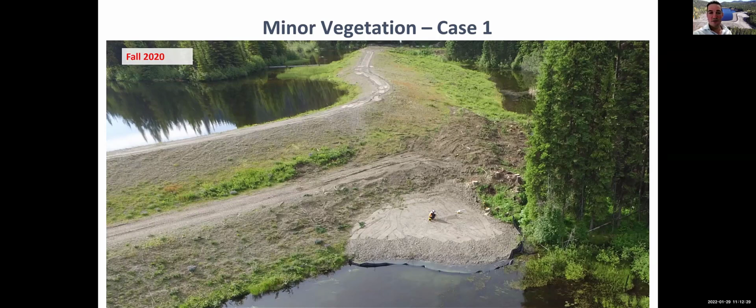So we did a rapid conventional filter, essentially a blanket filter, and repaired this thing. They have some increased monitoring and other things, and you can see we talked about that screenshot. I said if you're going to screenshot something, on the downstream slopes and not the crest area, anything bigger than 8 inches, cut off. So you see some pretty big stuff cut off.